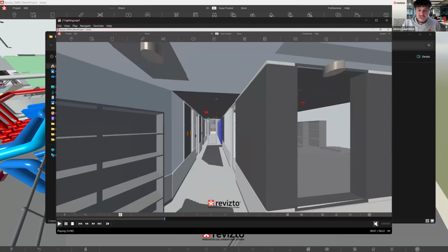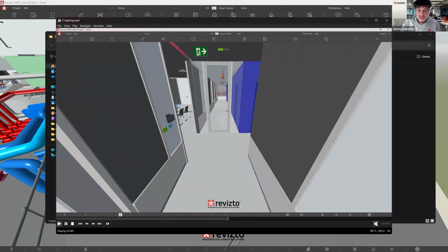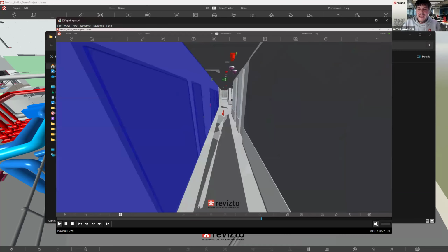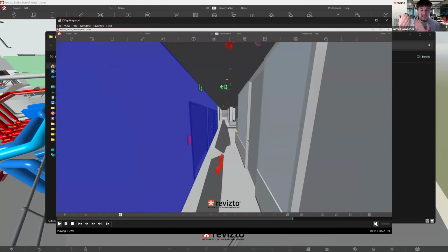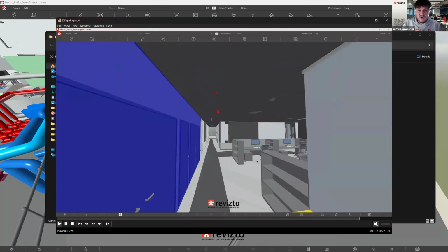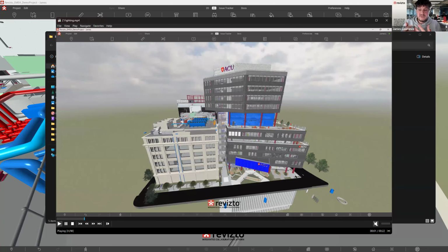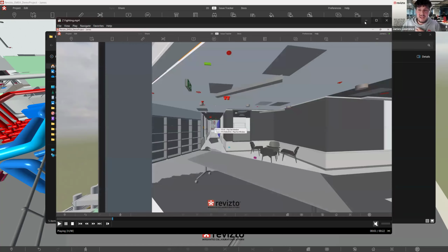And as you can see, we have what we call Z fighting on those floors. It almost looks as if there's an error in the modeling because those two items are flickering against one another, and it can cause quite a few issues. People think it's graphical issues. It's just been the way that Unity has been built. And basically, it's one of those items that we've been trying to develop for some time.